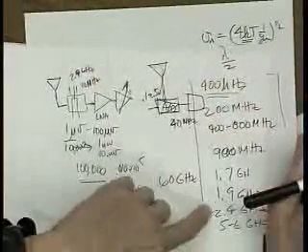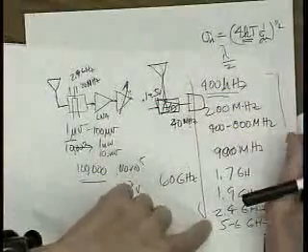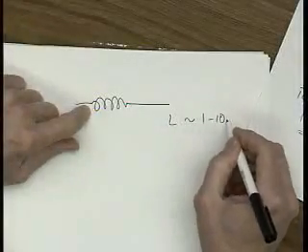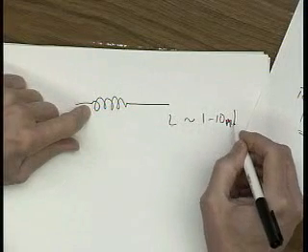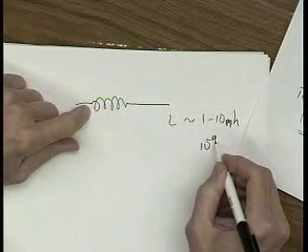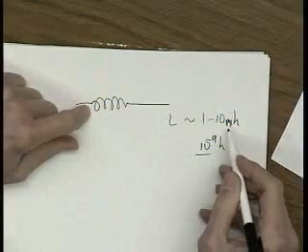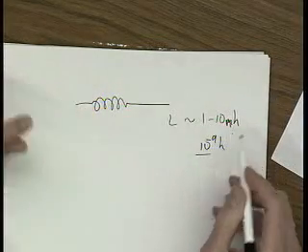It's when we started getting up in these gigahertz signals that the inductor sizes we needed were on the order of 1 to 10 nanohenries. Okay, that's 10 to the minus 9th henries. That's like farads, right? Once you got in this nanohenry regime, you could put them on a chip.